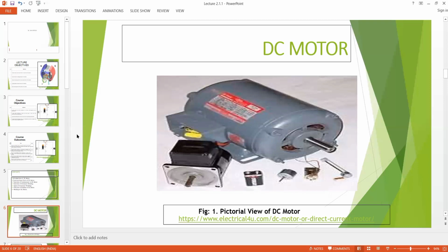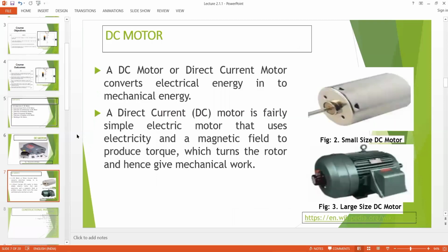We require windings, and we have two types of winding: armature winding and field winding. Which is more inductive? Field winding. Armature winding is less inductive as compared to field. If I talk about winding resistances, if armature resistance is 0.1, then the field winding would be 10 times, or 100 times, that. That is the relationship for the speed control of the machine.